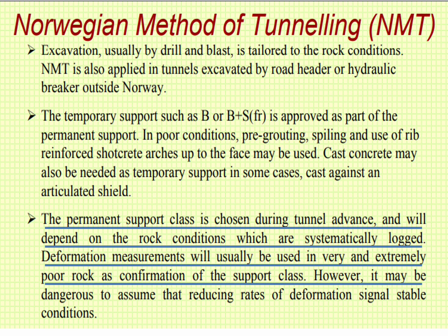The permanent support class is chosen during tunnel advance and will depend on the rock conditions, which are systematically logged. Deformation measurements will usually be used in very and extremely poor rock as confirmation of the support class. However, it may be dangerous to assume that reducing rates of deformation signals stable conditions.